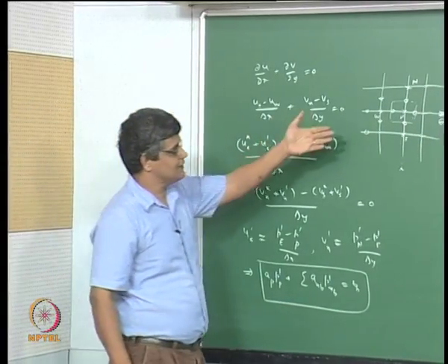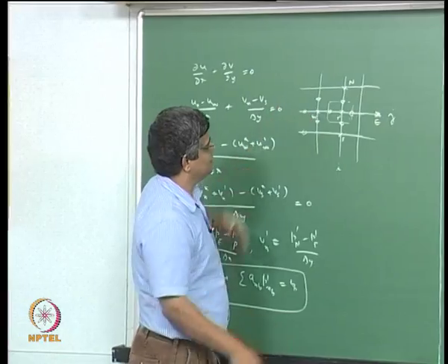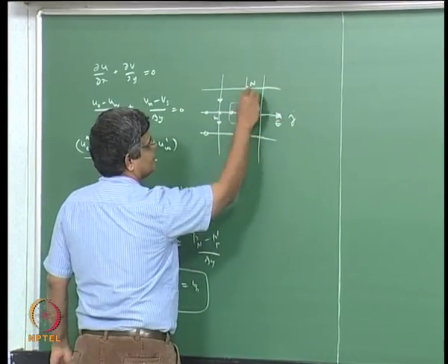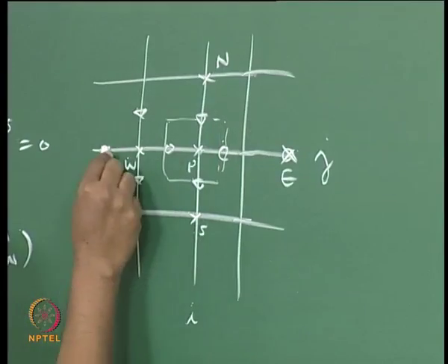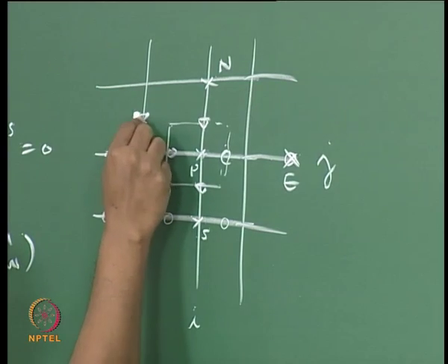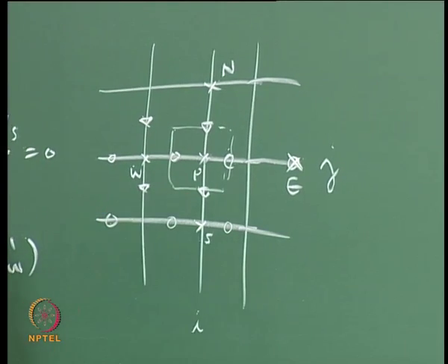We have made use of a staggered grid approach. So this meant that you had a grid like this for the pressure, and you had a separate grid for the u velocities, and even a separate grid for the v velocities, and so on.